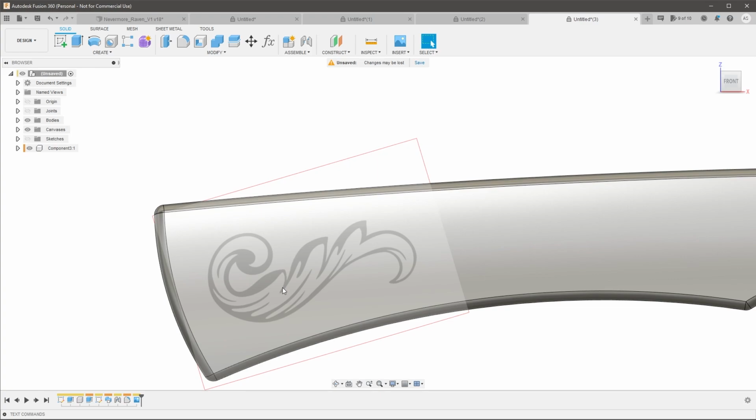Now, if I actually really cared, like the arc from here is 2 inches and it's sweeping along a very specific path, then I would probably invest the time to go ahead and dimension it and sketch it with the proper tools. That way I could update something later if I wanted to. But since you don't care and you're just basically tracing out a generic shape, a spline works great.